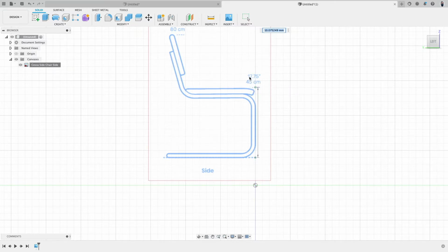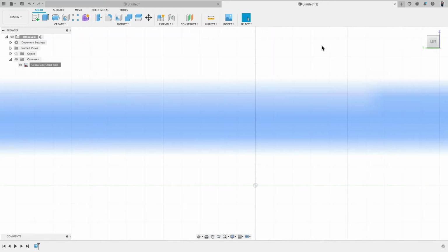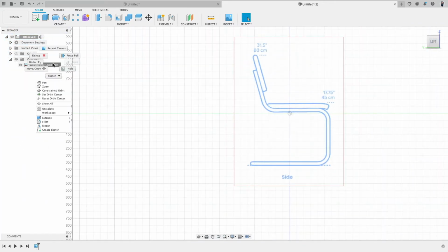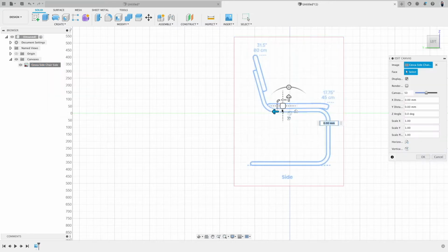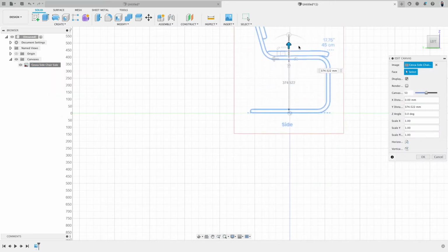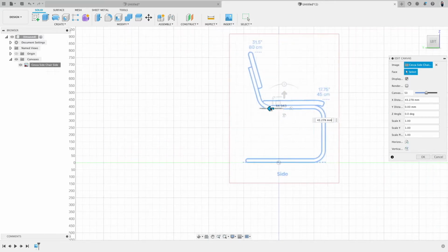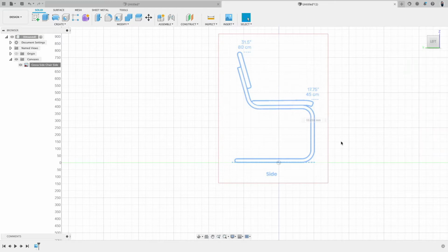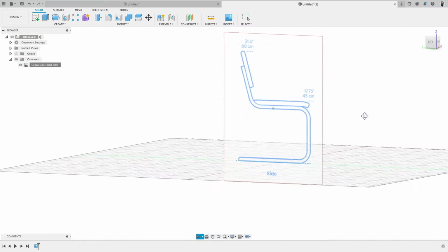And you see the dimensional measurement is really nice and vertical straight. So that should be 45 centimeters or 17.75 inches. I work in millimeters, so this is 450 millimeters. Or I type in 45 centimeters. Click OK. Very good. Now I can right click and move this image up. Very good. Maybe to there. Left and right doesn't really matter. Cool. So we have the side.